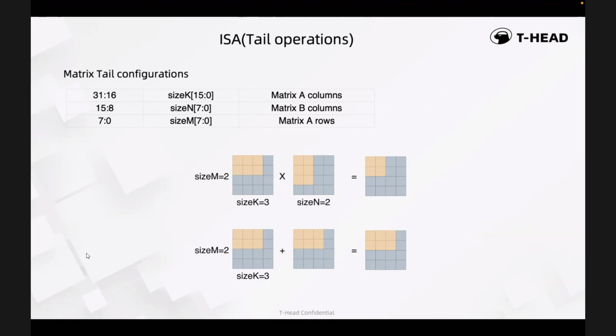So do you have any communication between your matrix registers and your vector registers? Any way of communicating without going through memory, through loads and stores? We just do it through loads and stores because we think making some connection between matrix registers and vector registers is too difficult for physical implementation.